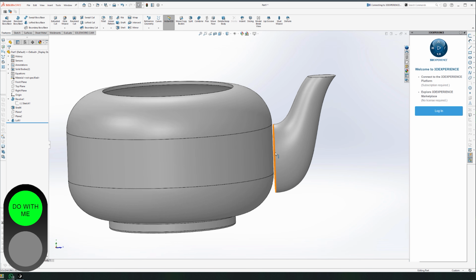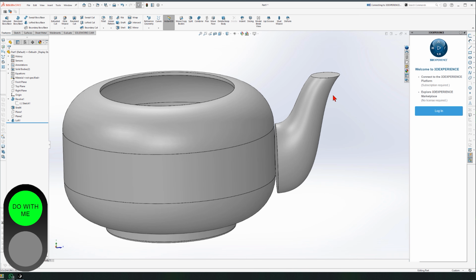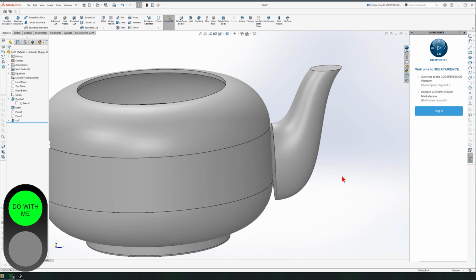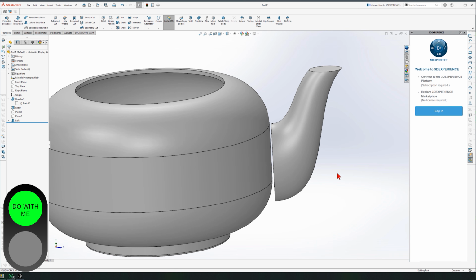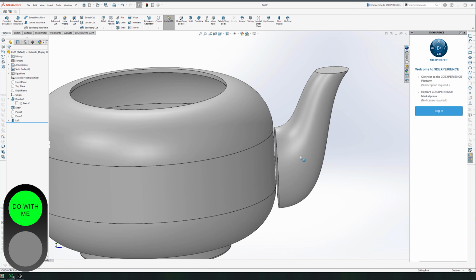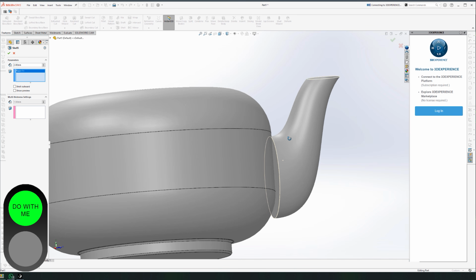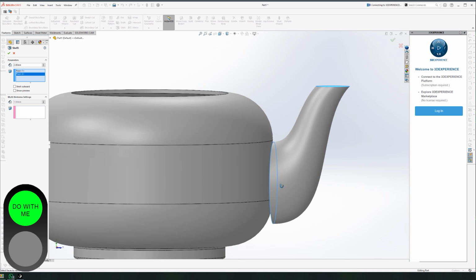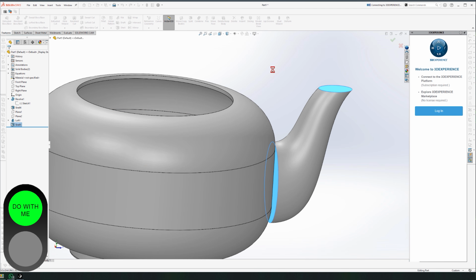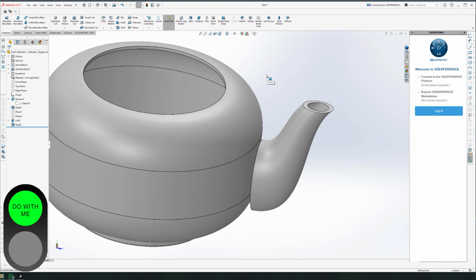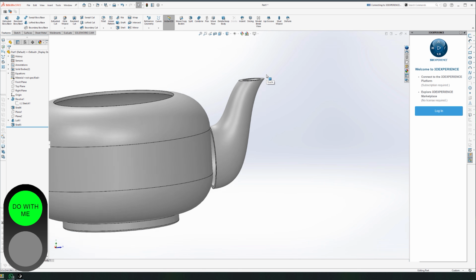We have a few things to do. Connect it to the body and make it hollow. How do we do this? Before I connect this to the body, I would like to make it hollow. So I go to shell. The 2mm is good. We pick this surface and this surface. We want to have these two open and connected. So we click OK. This would give us this. Okay. We are now looking at a hollow part.